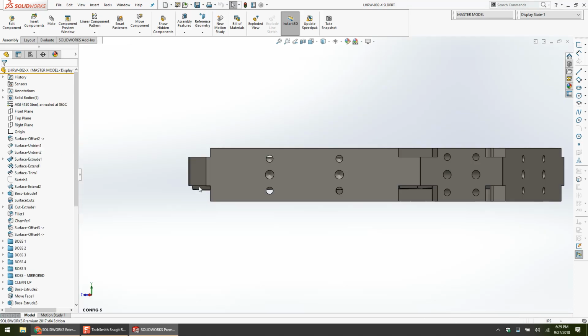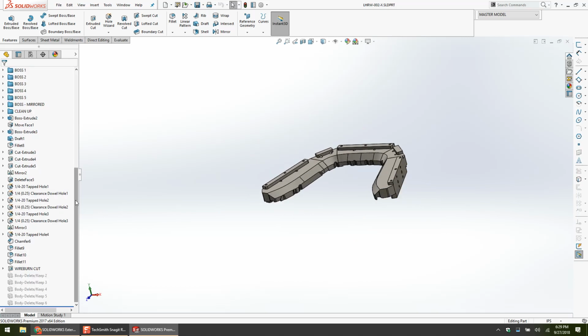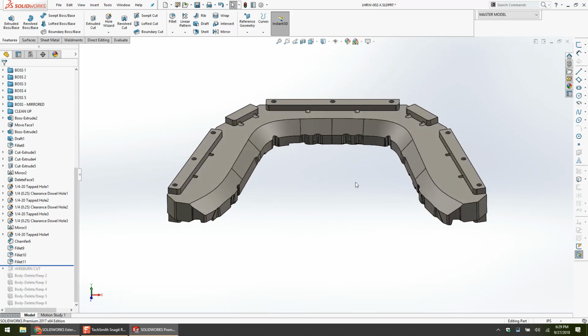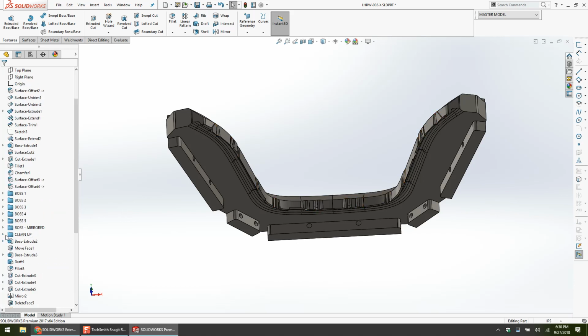So if we look at this jaw design here, I had very tight tolerances. If anyone's ever done edge wrap machines, you understand the challenges with this. But it's basically like, here's the plastic part. We don't have CAD for the vinyl or the foam or the foam-backed vinyl or cloth or whatever. So they give you the part and then the cloth. Then you measure the cloth and see how much crush it has. And then you kind of take a best guess. And you start offsetting the part and you design your edge wrap tool. So this is the edge wrap tool. And here's all the features used.